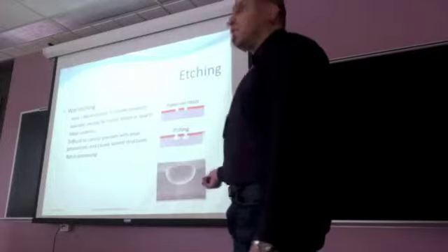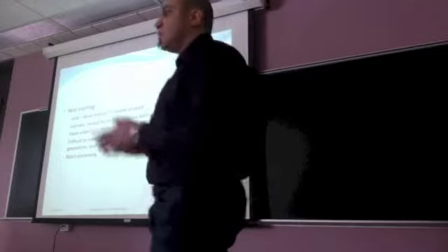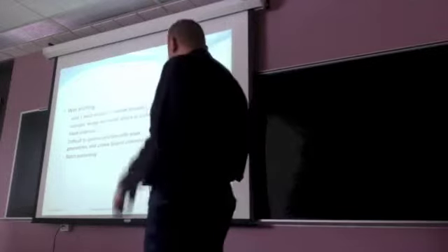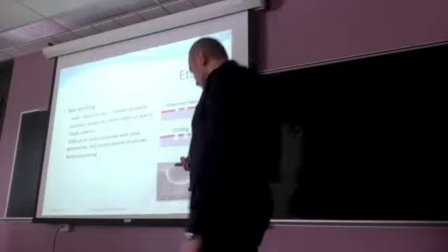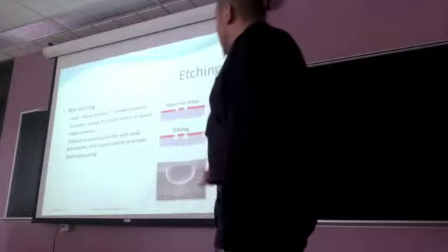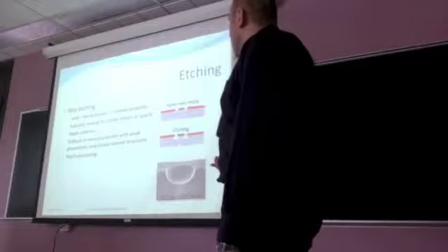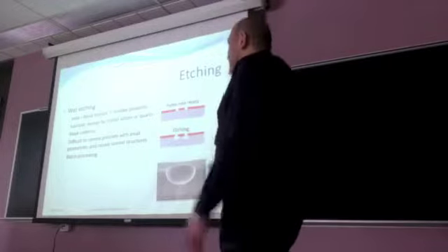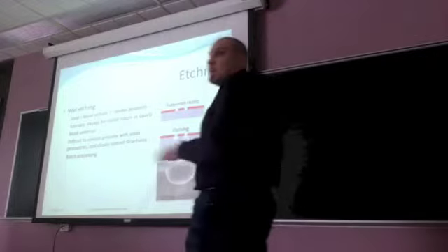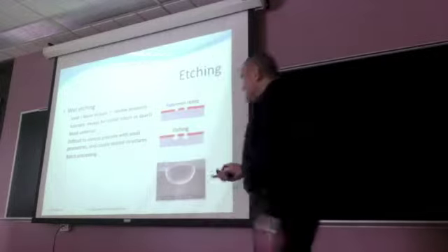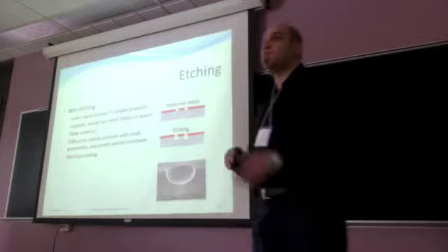But there is one exception, especially for crystals. And in the next slide, I will talk about wet etching of crystal silicon. During wet etching, mask undercut can also occur. And due to this mask undercut, it's very difficult to control precisely with small geometries and closely spaced structures. However, the main advantage of wet etching is batch processing, which means that you can process 25 wafers at one time in industry.